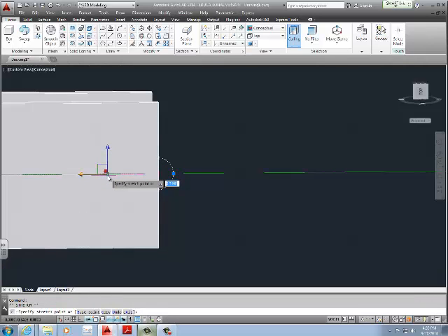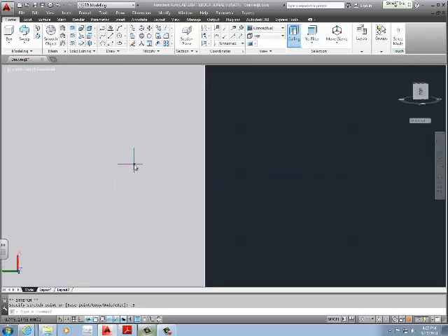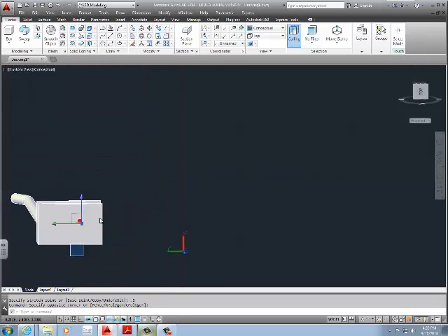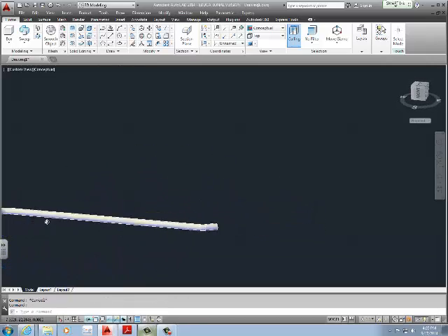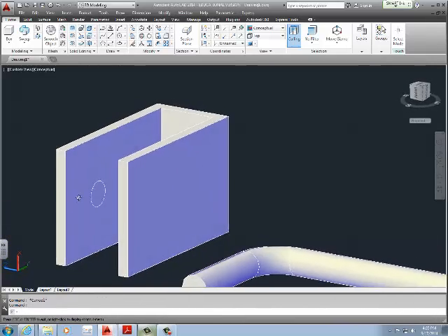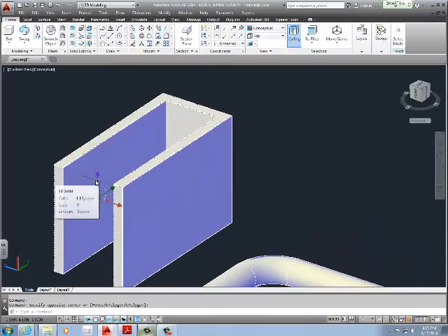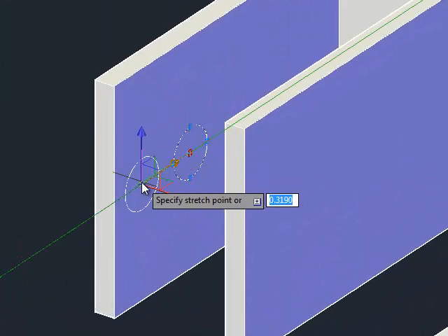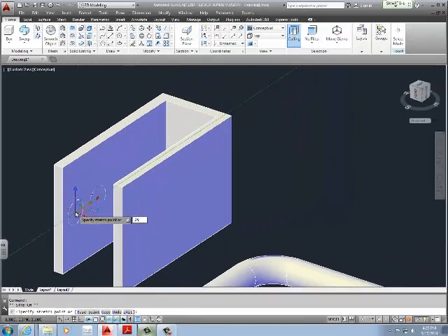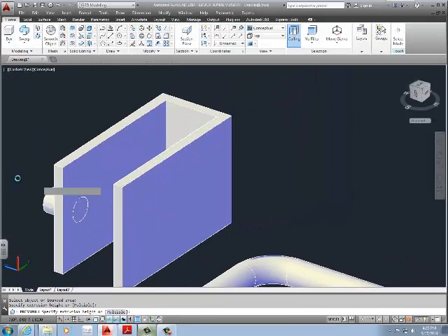We're moving it over, let's say about 1/2 inch. Again, there are no specifications on this, so you could specify whatever you prefer. Otherwise, you can follow me as I'm doing it. I see that it's a little too far, so I can bring it back down 0.25. And from there, I do a press pull, and that cuts that hole right out the back.